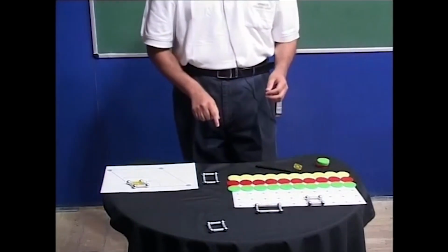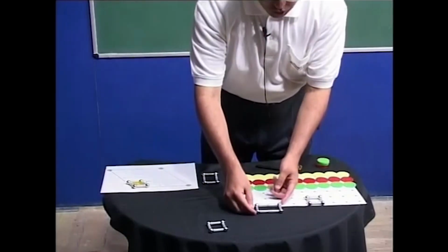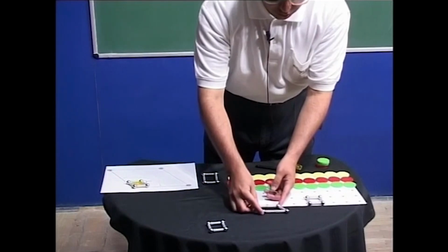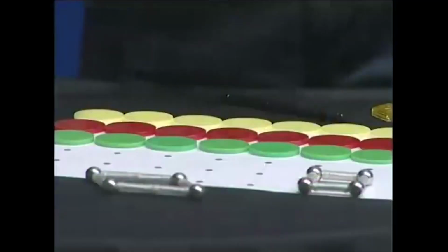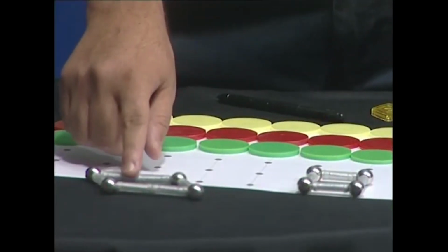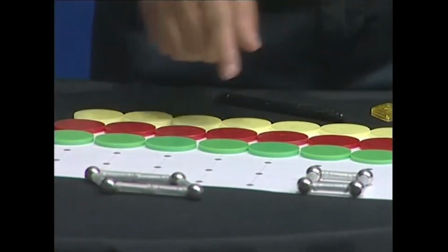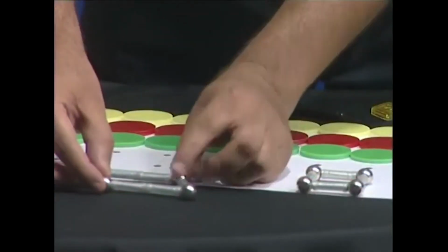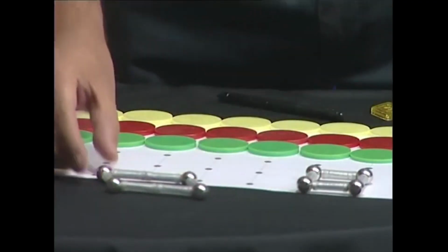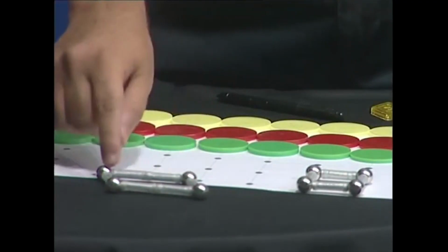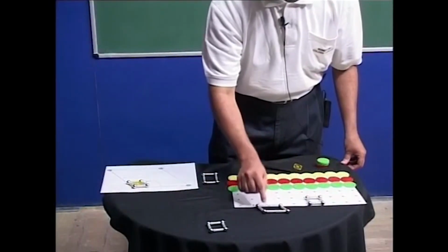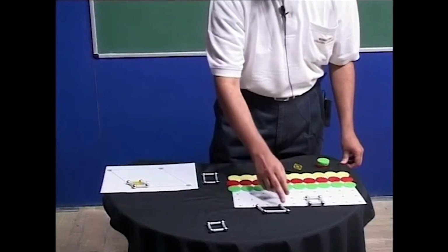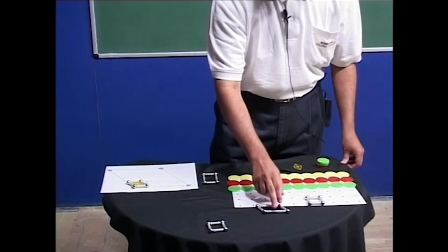I can further perform a simple experiment of trying to distort this unit cell. Once I distort this unit cell, clearly this unit cell has transformed into a parallelogram unit cell. This included angle can be any angle depending on the kind of distortion I am imposing, and even after the distortion you can clearly see that the two opposite sides are parallel, and therefore this is a parallelogram unit cell of the most general type, wherein there is no constraint on A or B or on the included angle.